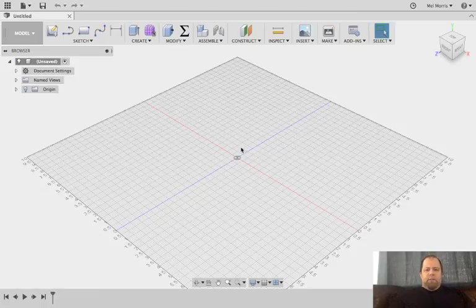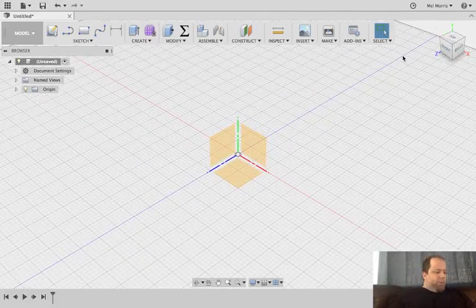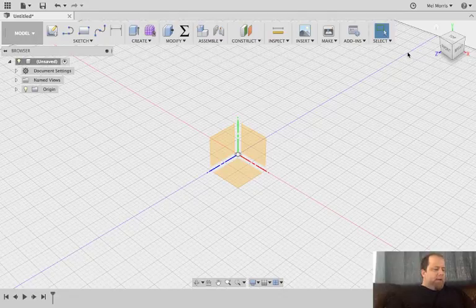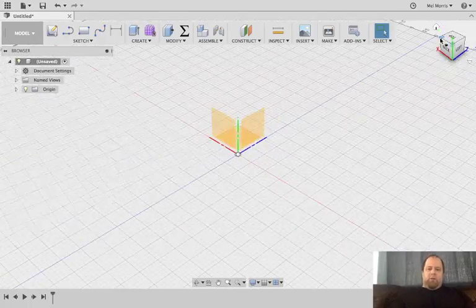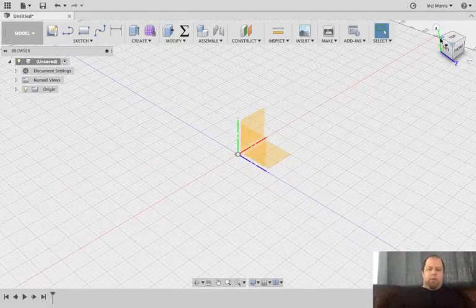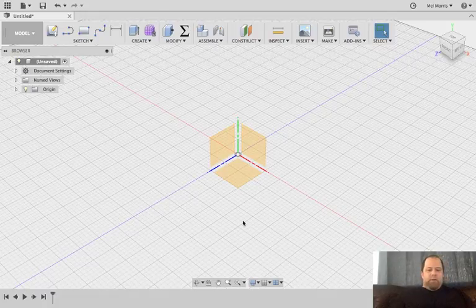So basically what you're looking at, turn on origin. The origin is this button up here, which will show you your axes. So this is your front face. If you're not familiar with navigating, there's a little home button in your top right corner, which will automatically put you into that isometric type view. You can also hit that corner right there. If you want to spin around, you can hit each corner, and it'll spin around from center on your view. And if you want to go back to home, which is the default setting, this is what you're looking at.